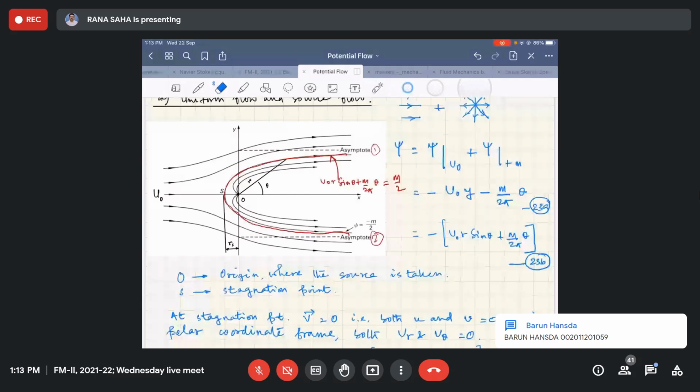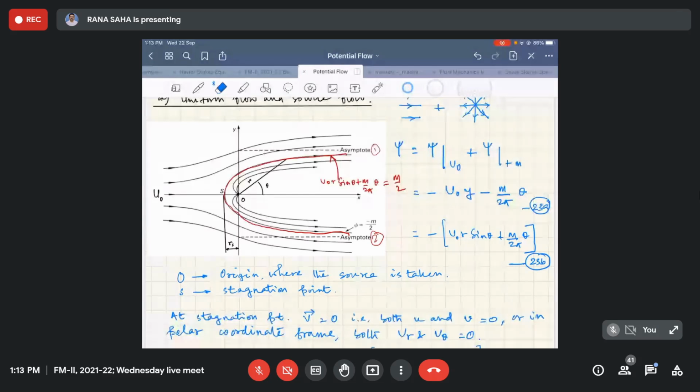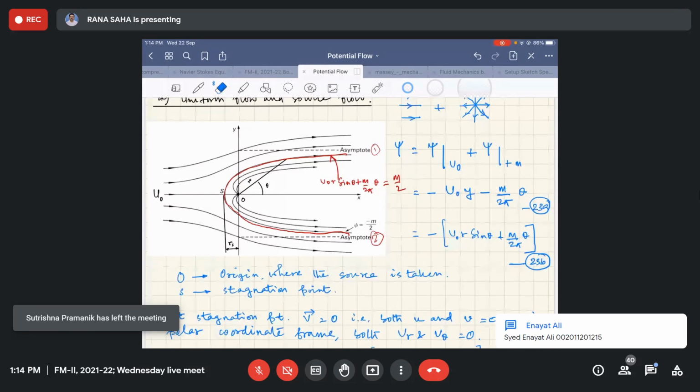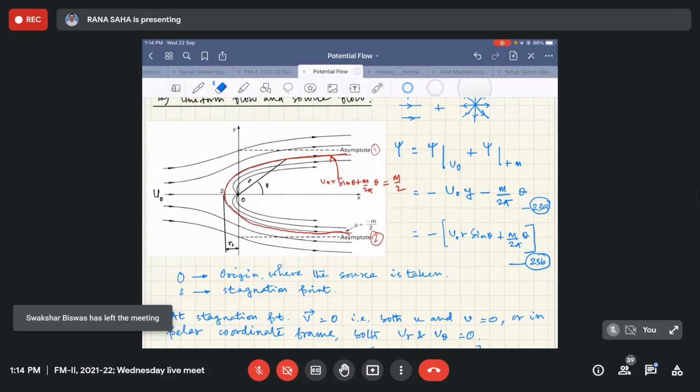So that is one major importance of finding out the stagnation point, followed by the equation of the streamline passing through the stagnation point. So that particular streamline, the contour that it represents, if you solve that particular streamline for different points in the flow field, you can get a curve or a contour. So that contour can be thought of as a demarcation between two distinct flows.